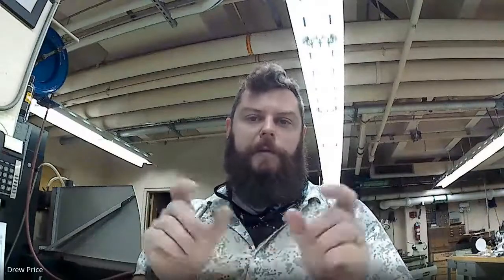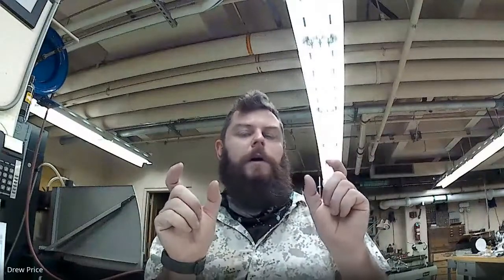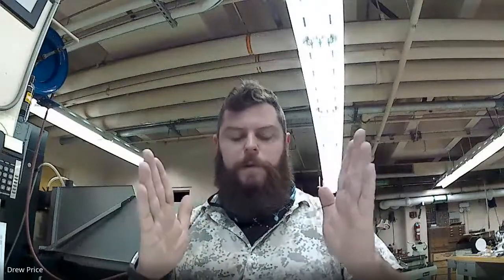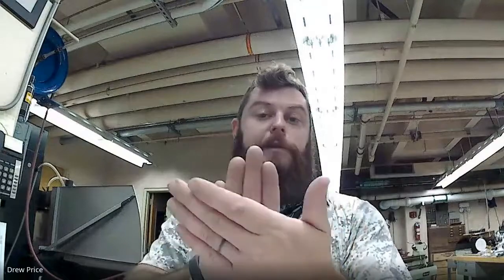So when you're going through your lab activity and you've measured duplicates of whatever you've been able to get to in your place of residence, when you're going to design the holder or the thing that those pieces interface with, give yourself a little bit of buffer room. If you didn't happen to measure the absolute largest part in that distribution or the smallest part in that distribution, make sure that you design your part in such a way that all of the possible ones that you might encounter would actually fit into that part.